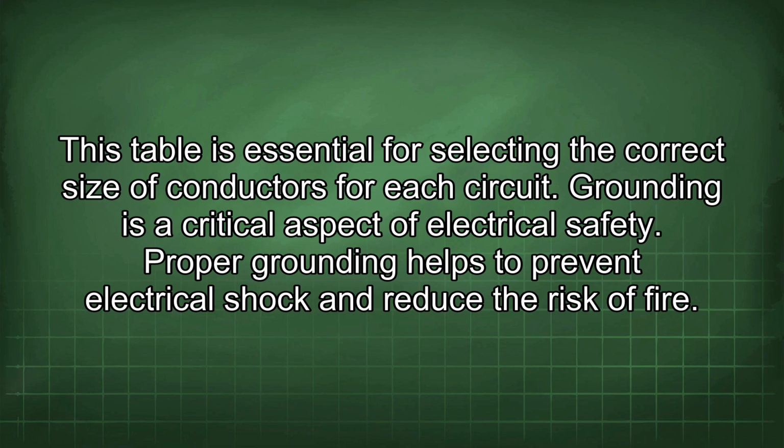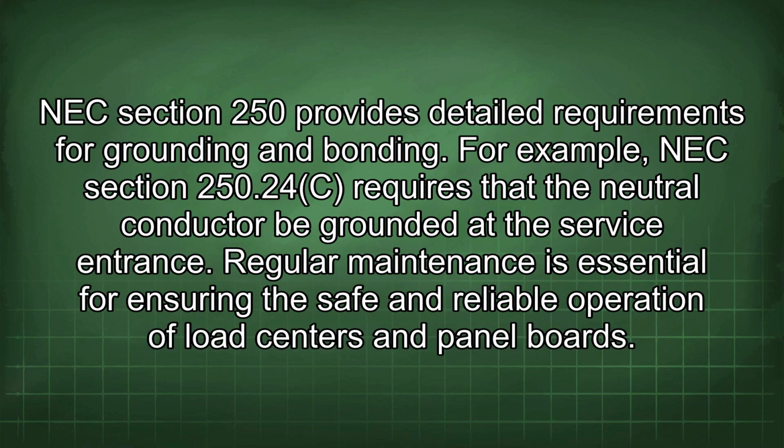Grounding is a critical aspect of electrical safety. Proper grounding helps to prevent electrical shock and reduce the risk of fire. NEC Section 250 provides detailed requirements for grounding and bonding. For example, NEC Section 250.24(C) requires that the neutral conductor be grounded at the service entrance.